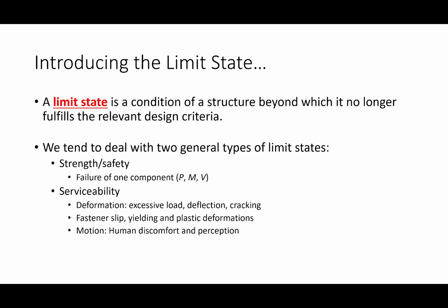That L over 360 comes from day-to-day intended use. So I'll tell you where that limit comes from. How many of you have ever been in a house that has a plastered roof? Like the roof has a plastered roof or a drywall-based roof and whatnot. So if you start exceeding L over 360, the plaster will start to crack. Has nothing to do with the building falling down and killing people, but the building's not serving its intended function if it deflects that much. And while that limit came from plastered roofs, it does tend to work pretty well for framing of structural systems in general, so we use it pretty liberally. And so that's one service limit state.